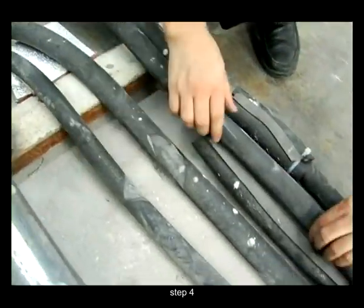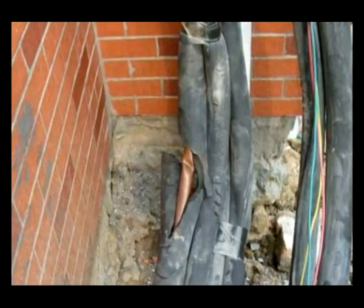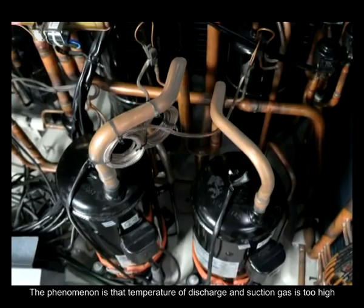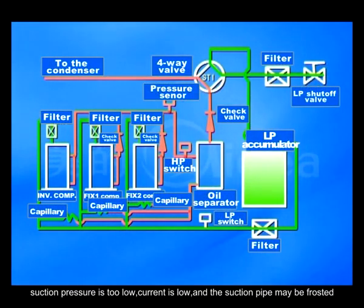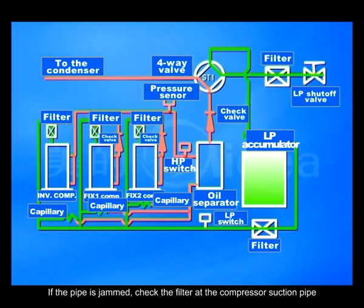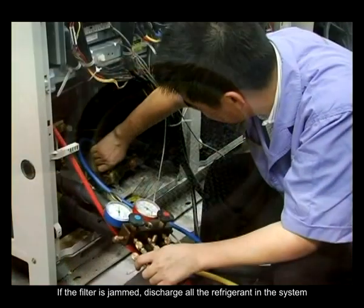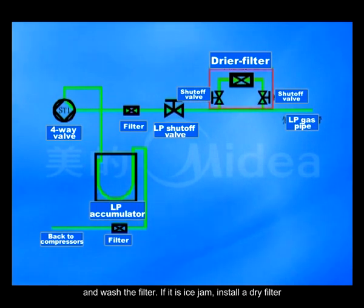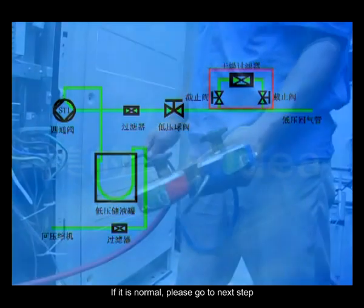Step 4. Check if the pipes of low pressure side is jammed or deformed. The phenomenon is that temperature of discharge in suction gas is too high. Suction pressure is too low, current is low, and the suction pipe may be frosted. If the pipe is jammed, check the filter at the compressor suction pipe. If the filter is jammed, discharge all the refrigerant in the system and wash the filter. If it is ice jam, install a dry filter. If it is normal, please go to next step.